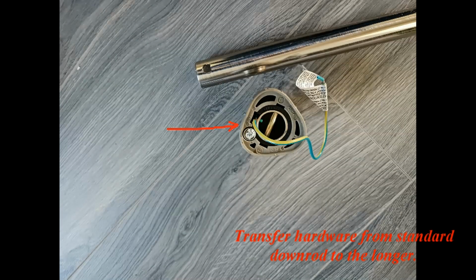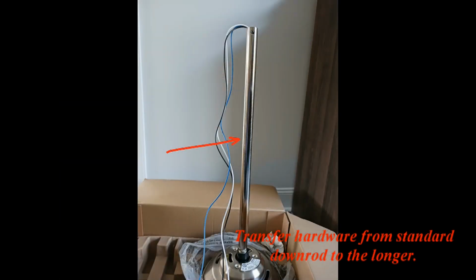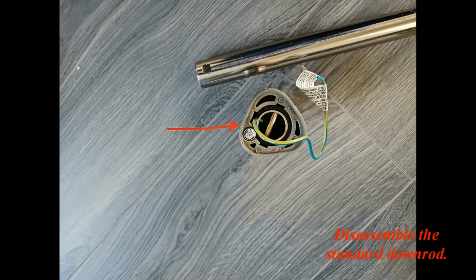Transfer hardware from the standard downrod to the longer one. Disassemble the standard downrod. To do that, first of all unscrew the top screw. Next, slide down the downrod hanging ball and remove it. Remove the metal pin. Remove the plastic opened bushing. Unscrew and remove the downrod grounding screw and wire.